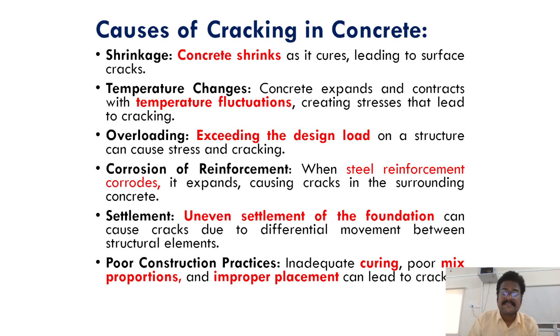Then the last reason is poor construction practices. Inadequate curing, poor mix proportions, and improper placement can lead to cracks. These are the various types of cracks. My dear students, please address these cracks as a civil engineer at a very early stage.